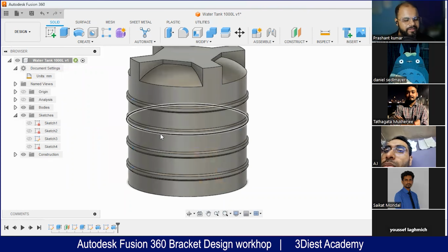We'll activate that. We'll select all the sharp corners one by one like this. Here you can see. There are some quick ways to select all these profiles, but we're not going to learn that. But you can select one by one all the 4 corners. There you can see I have selected. Then we'll give it a fillet of maybe 0.1 millimeter or something like that.